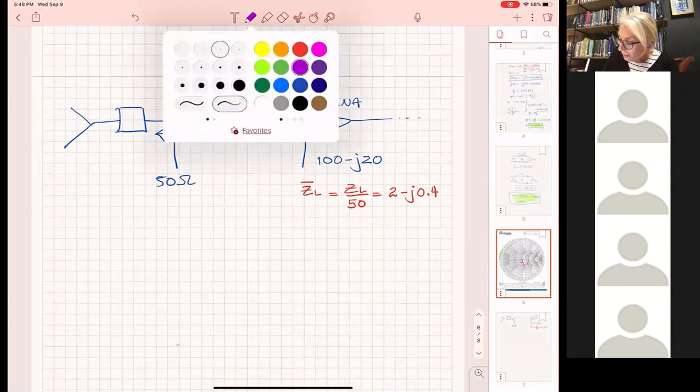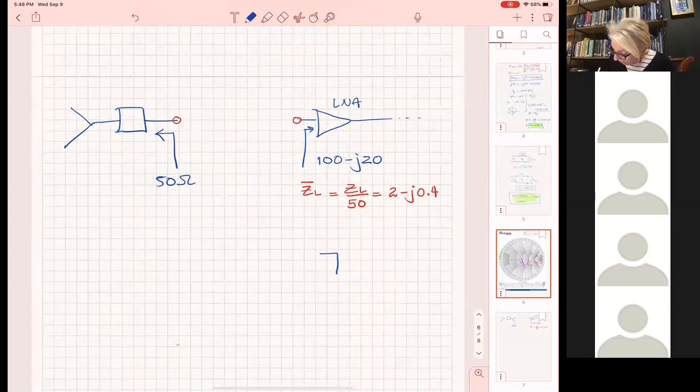So here, we had a load at the end, which is the low noise amplifier. And then in the Smith chart, the easiest thing that I did is not the same one that I put on paper analytically. That is a different one. It is one that starts with a transmission line and ends with a stub.